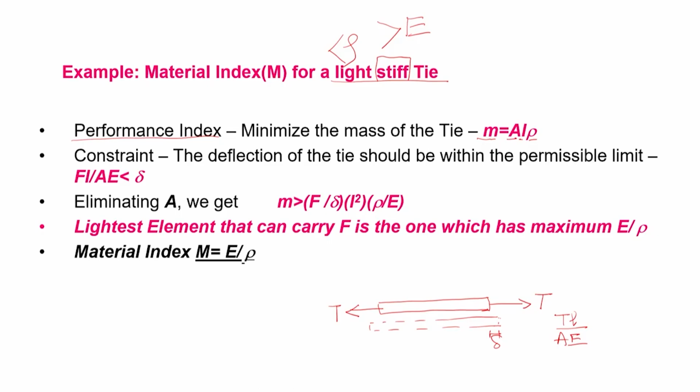So, now I am looking at what is then my mass? Well, in my mass we have area of cross section, we have length, we have density. Length of a tie cannot be changed because it is connecting between two members. Density we are looking for. So, it is the area only which is the free variable, that is very important. So, that means area from this particular relationship can be written as what? M by L rho.